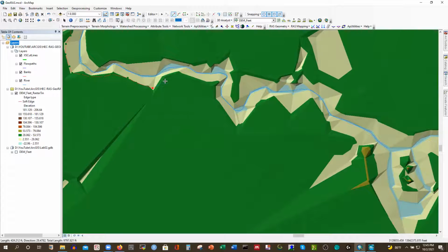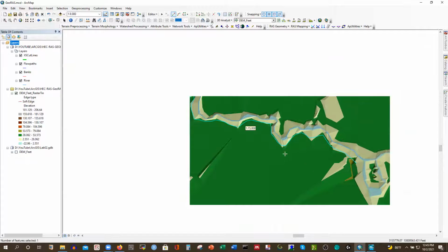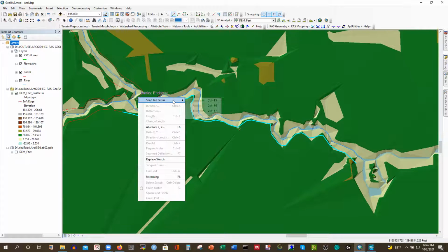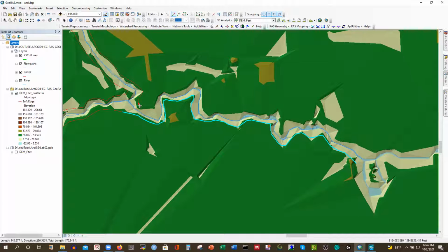Yeah. So in this window I can finish off. So here it is. Just follow this white line as you can, but you have to even capture all this bend pretty smoothly, right? I'm done. And now I have to do the same processing there. Click there, right click, snap to right vertex. We have the vertex, and then follow the bank of the river pretty quickly.